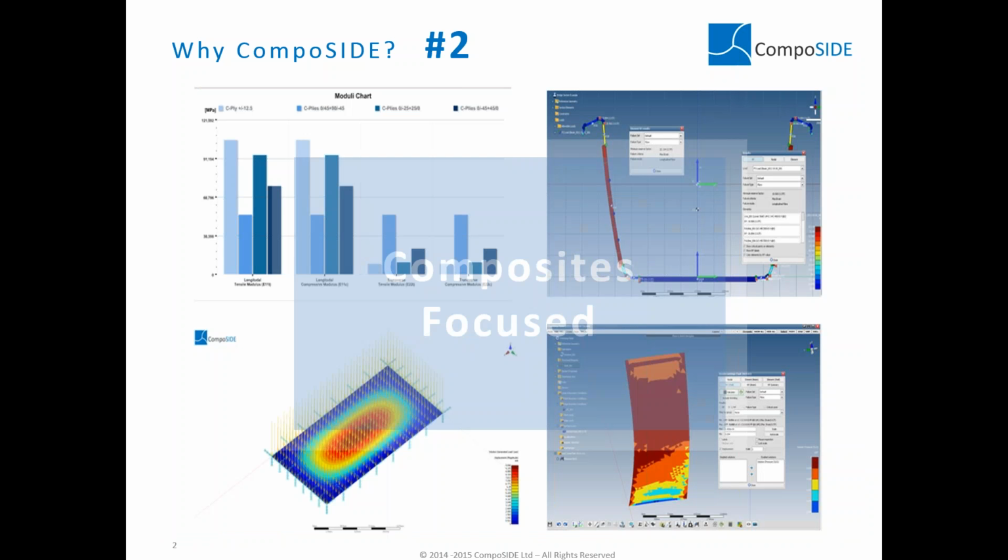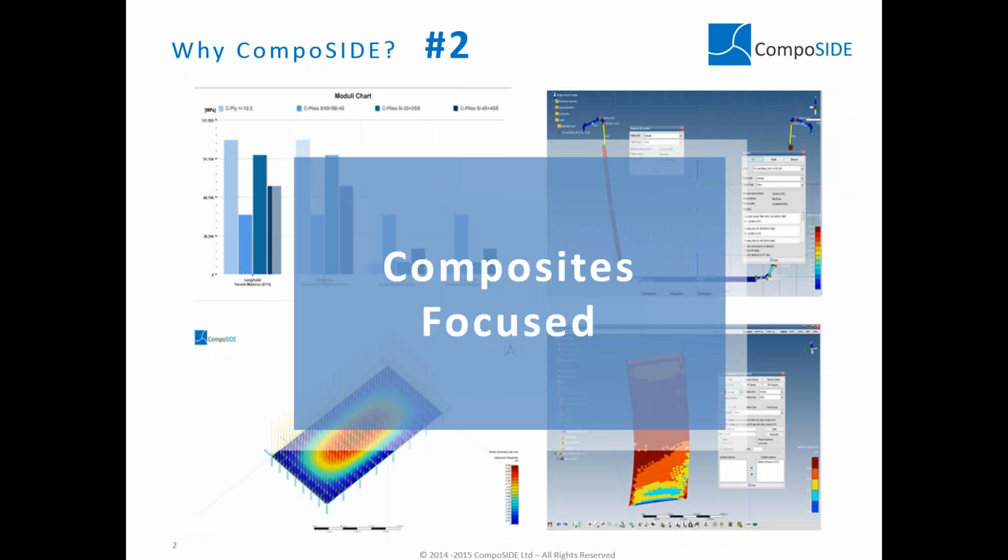The other feature, which we believe is quite important, is that this tool and also the bill of material was designed around composites, and the full focus is on addressing the needs and requirements of designing with composites and post-processing of data related to composites. So this bill of material generation tool has composite-specific things like usage and wastage factors and other things which are related to composite materials.